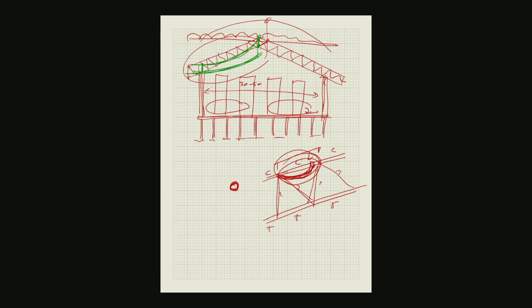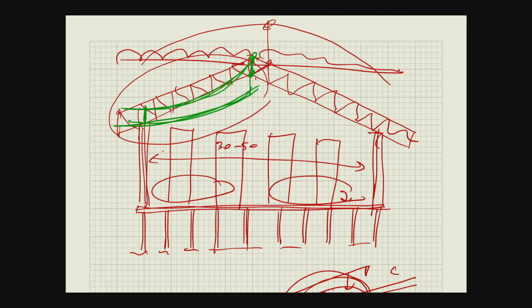So that's why you're going to have a sub truss, and you're going to wonder, why do we need the sub truss? Maybe the sub truss is in the middle part like this. It is just to prevent the out of truss plane lateral torsional buckling. The truss behaves in the same way as the beam. So lateral buckling is caused by the top chord under compression, and then as the top chord deforms, it goes laterally. The torsion comes along as a result.